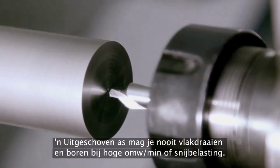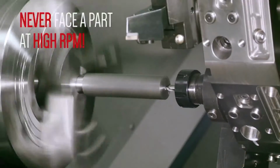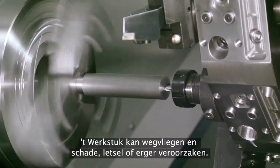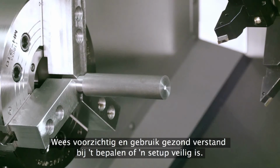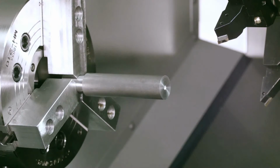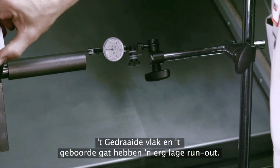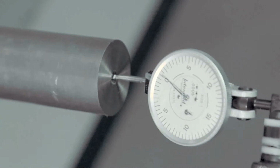An extended part should never be faced and drilled at high RPM or cutting loads. The part can be thrown and cause damage, injury, or worse. Exercise caution and common sense when deciding what's safe for your setup. With the facing and drilling complete, let's check our part. Both the face we just turned and the center drilled hole have very low runout. Great!